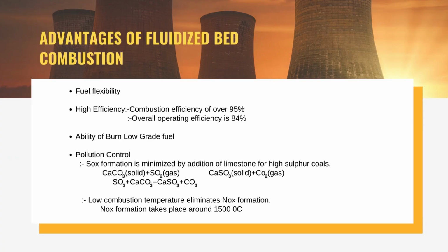Now, we will see the advantages of fluidized bed combustion boilers. Fuel flexibility and high efficiency: combustion efficiency of over 95%, overall operating efficiency of 84%, and ability to burn low grade fuel. Pollution control: sulfur oxides formation is minimized by addition of limestone for high sulfur coals.